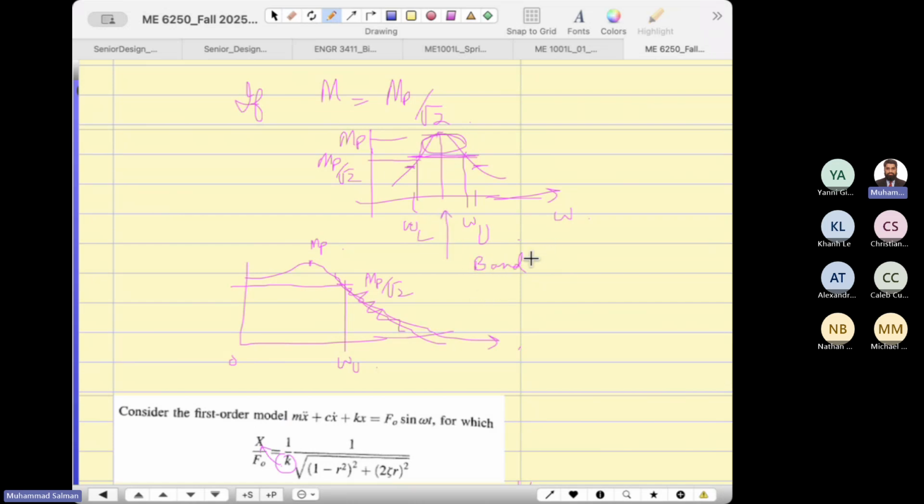Band pass means some frequencies can pass, maybe from 10 to 100. In this kind of device, transfer function or filter, when you are restricting your mass to respond only in a certain bandwidth, then you will automatically use the band pass. So we have to see where the mass responds. Then comes the displacement here. Let me show you.